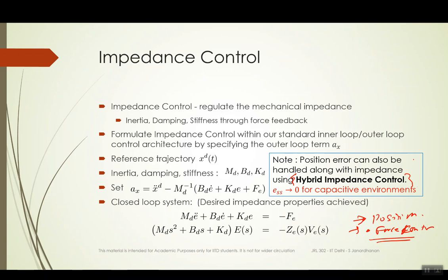Okay, this looks very similar to the case of a non-zero error. The hybrid control is applicable whenever your environment naturally has an integrator in it. A natural integrator in the environment would mean that the steady state error will go to 0, like adding the I component in a PID controller. This natural integrator is going to ensure steady state error equal to 0 in addition to the desired force Fe being applied.